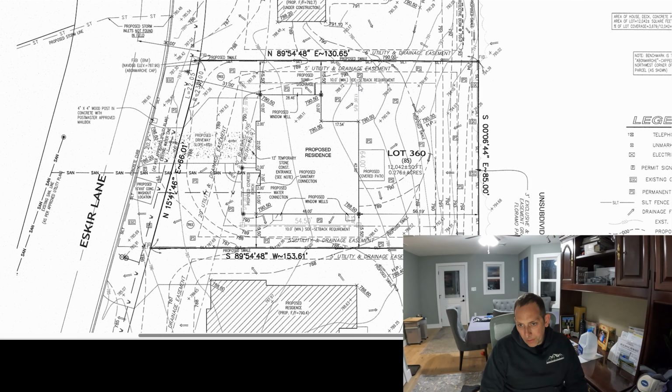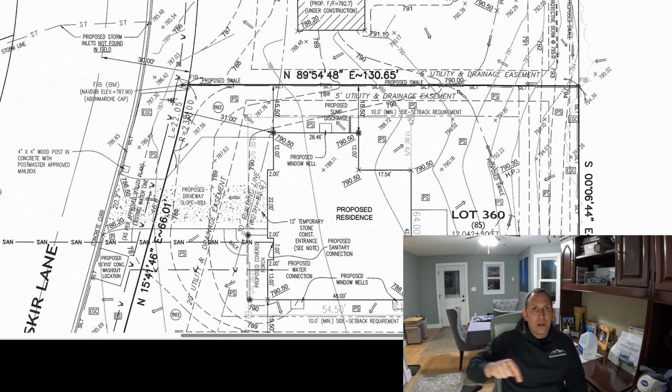On the back of the house, the line between the 2 stakes is the back wall of the house, the exterior of the back of the foundation. And then when we come to the front line here, it touches the furthest front concrete wall on the house, which is going to be for the covered patio. And the other thing you can see in really faint letters here, I'm going to zoom in a little bit. So now that these stakes are in the ground, you can run a string around all 4 of them and start snapping some dimensions. So what we know is this corner of the house is 17 feet from the stake, and we already know that straight line is the back wall of the house.